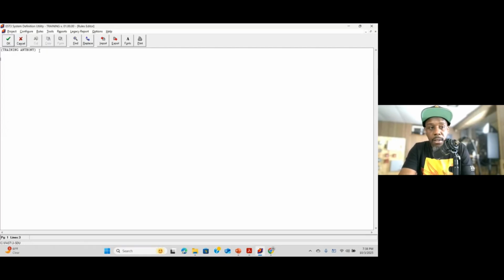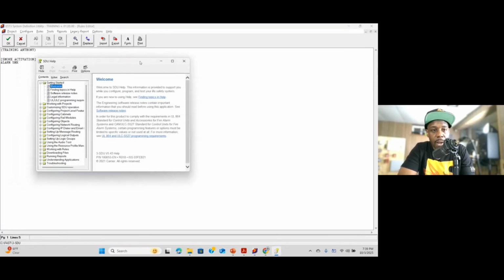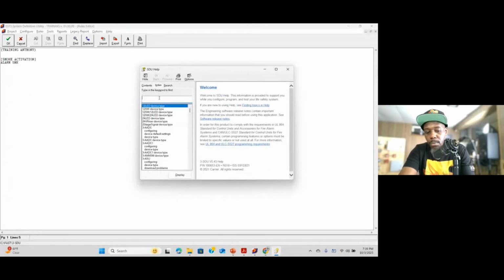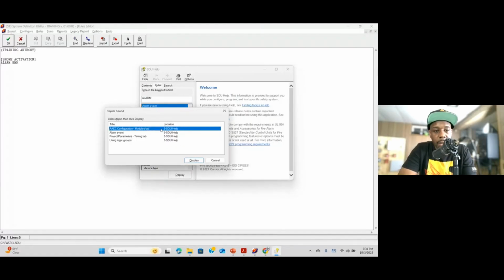So we want to write the rule. What is the rule label? What are we doing? Let's just say smoke activation. So we got the rule label. Into that we go alarm smoke, and we can use SMK or S or spell the word out. A lot of what I use is the help topic. If you're sitting there trying to write rules, trying to figure out what a qualifier is or whatever, you can just go straight to the help.